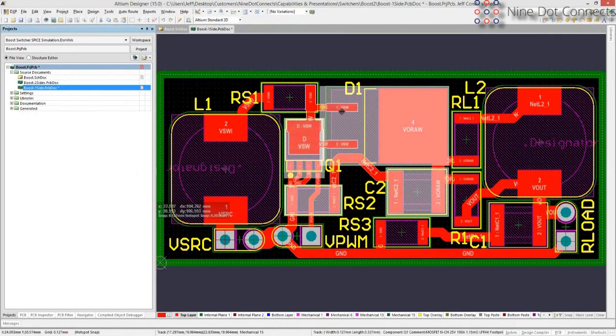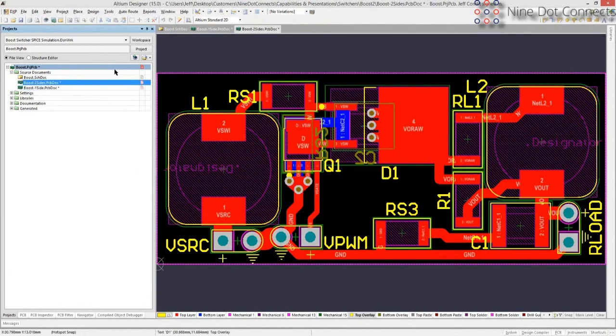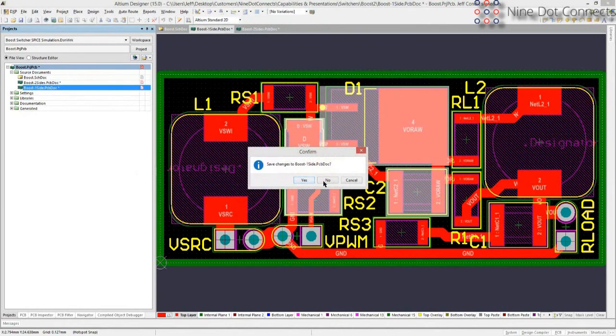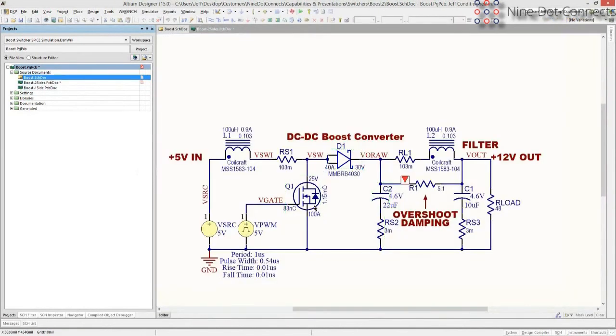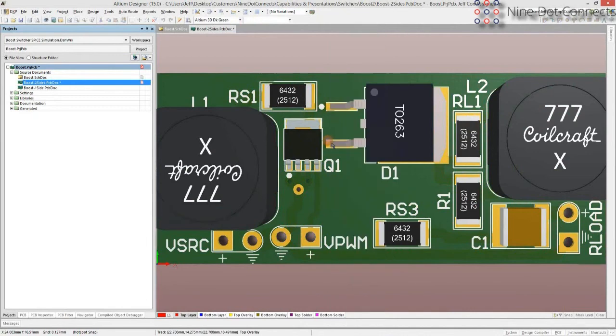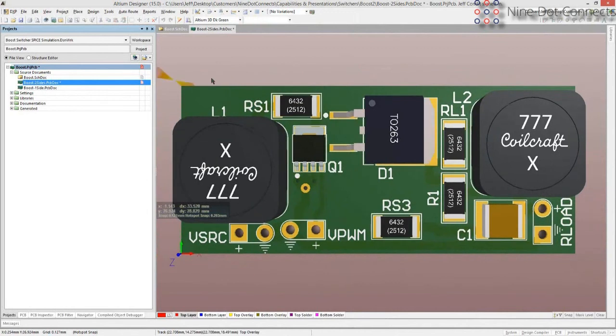Ideally, they would be laying directly on top of one another, broadside coupled. We can't do that with a single layer type interface. So we can consider a two-sided board. And we'll reselect those. Now you'll see that the parts laid on the bottom side are directly underneath parts on the top side, so the two current paths actually overlay each other. All right. We can simulate this if you like.